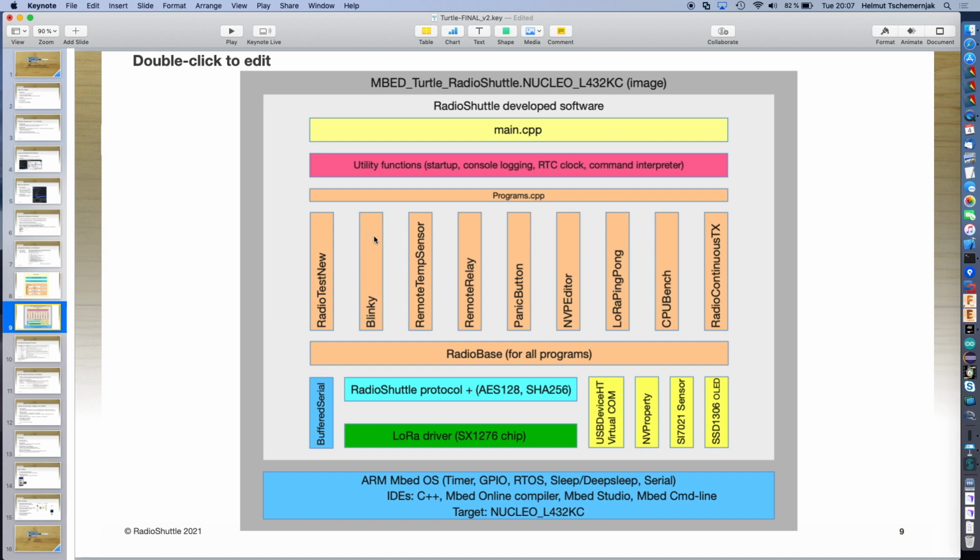Then for starters, we have a very simple application. It's a blinking application which just blinks an LED. But it's a little bit nicer than just blinking, because the blinking gets done via timers and everything gets done asynchronously, which means during the blink phase, the whole board will go into deep sleep mode, and when the next timer occurs and blinking is over, it just turns off the blink, etc. So just to get a very basic example, we included this.